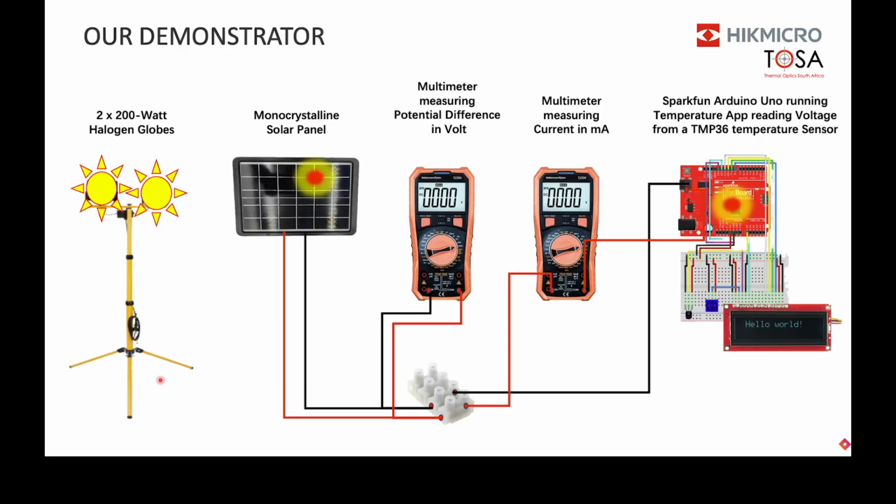Let's say there's, on the right hand side, you see there a hotspot created. Let's say there's something happening on the panel between the cells that shows up as a heat image. If there's a connector problem, that shows up as a heat image. Any connection along there, you'll see a heat image coming off, and if there's another component on the board, it'll show up as a heat image.